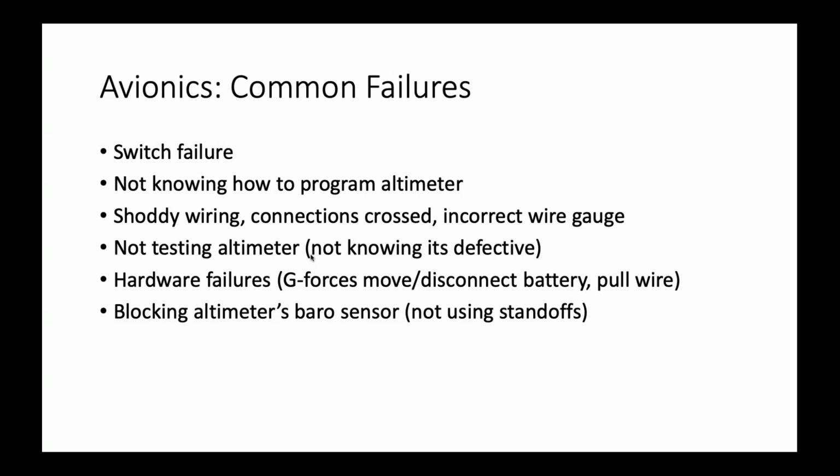And then testing your altimeter beforehand. That's not always possible, but it's a good thing to try, because some teams have had defective altimeters. Sometimes we just don't know how to program them, but sometimes it's an older one, or your team had a predecessor two years ago who used it and it was broken during that year, but that information wasn't passed down.